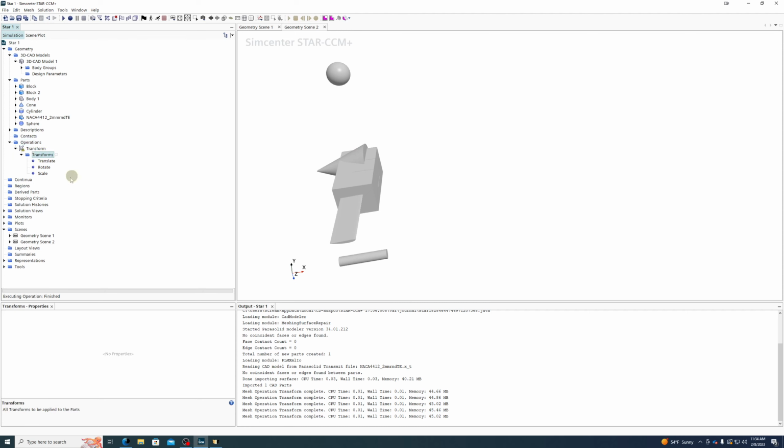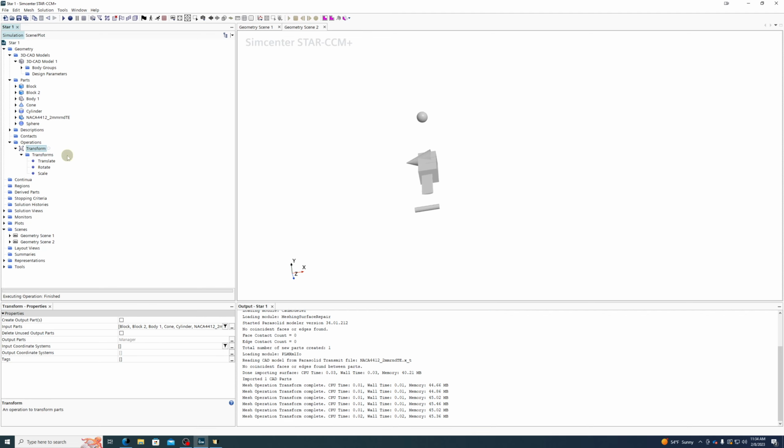You can also scale. You can make things larger or smaller. So let's do 0.5. And if we just want to do a uniform factor, we can just hit 0.5, and it'll apply it equally to all directions. So it just scaled everything about the origin by 50%.